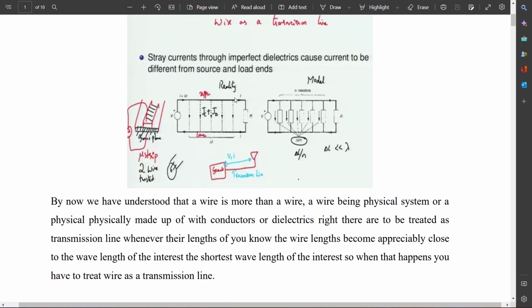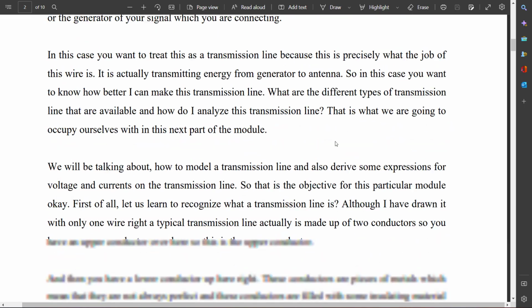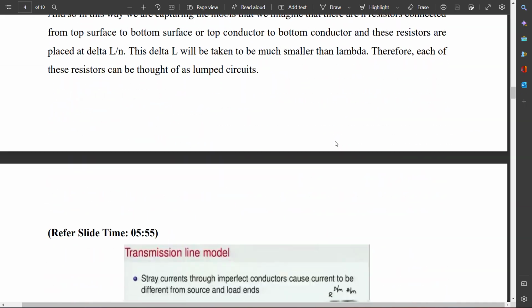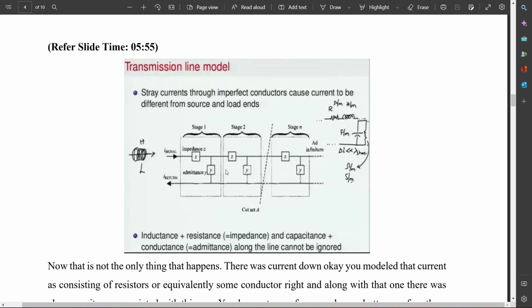Here, first the transmission line is like this, and there is a substrate in between these two transmission lines. For the transmission line, it won't be a perfect insulator. There will be some kind of conduction current as well as displacement current. So in a transmission line, in the series path we have resistance and inductance, and in the parallel path we have conductance and capacitance.